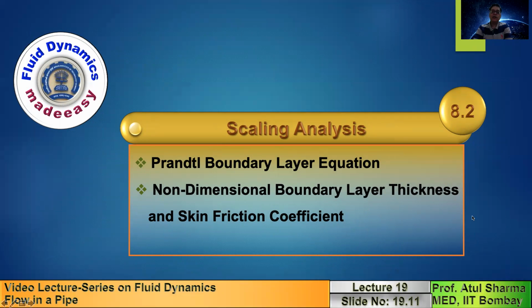Now I'll present a scaling analysis where I will show you a derivation of the governing equation for the boundary layer, which is called the Prandtl boundary layer equation. And using the scaling analysis, I'll present the functional form of the expression for non-dimensional boundary layer thickness and skin friction coefficient as a function of Reynolds number.